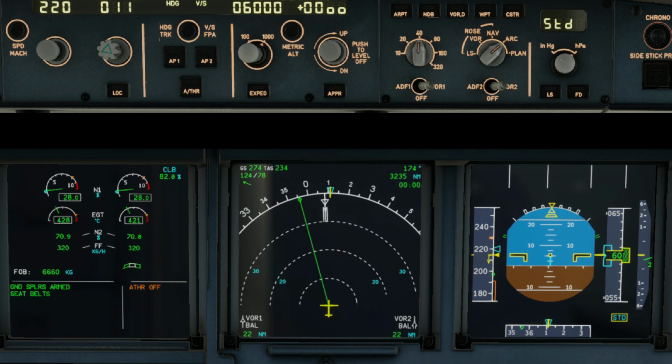You see, I close the thrust, we have a little tendency to go nose down. That's the pitch down effect of the thrust. And then as I add thrust, now there's going to be a little tendency to go nose up, but very small, because the aircraft has been set at 5 degrees and a half, and we are maintaining 5 degrees and a half. So it's constant pitch attitude maintaining.